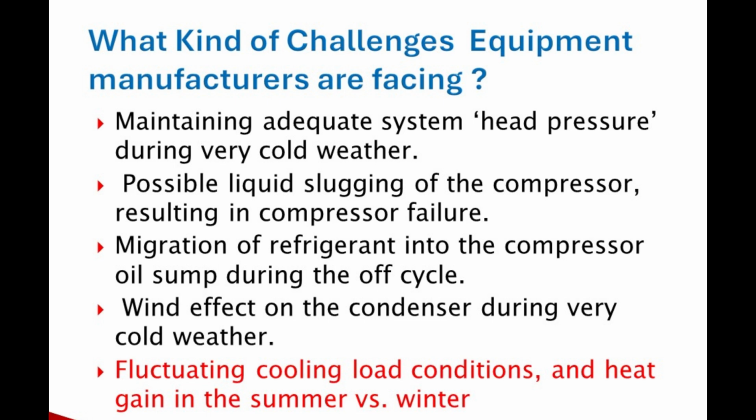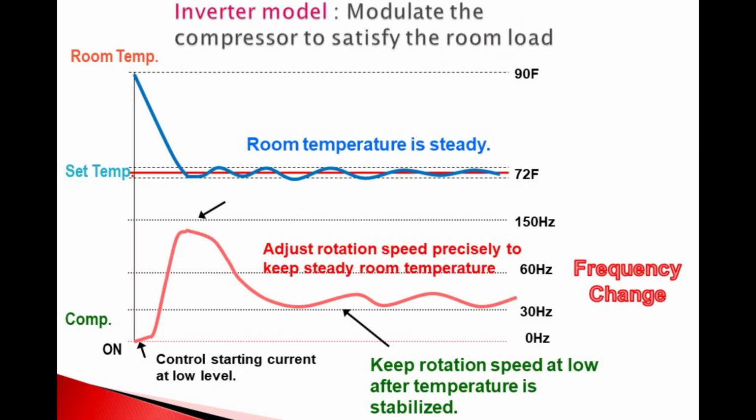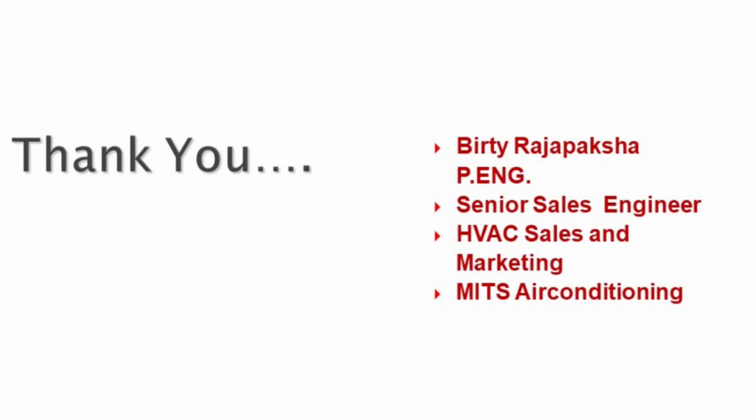You may have heard the term inverter frequently. But what does an inverter compressor mean? It refers to a compressor whose speed is controlled by varying the frequency of its power supply. This allows the compressor to adjust its capacity from 10% to 100% of its full capacity, resulting in very high efficiency. Now you may have understood, it's not just wind screens on a cooling-only unit. There are special hardware and software to overcome these issues. If these features are not available, the life of the cooling unit will drastically reduce.